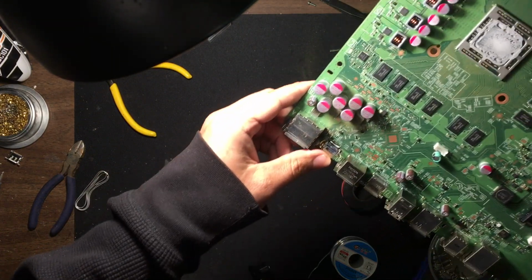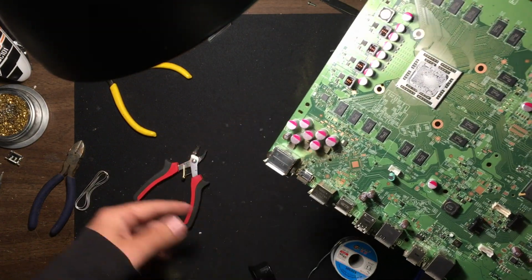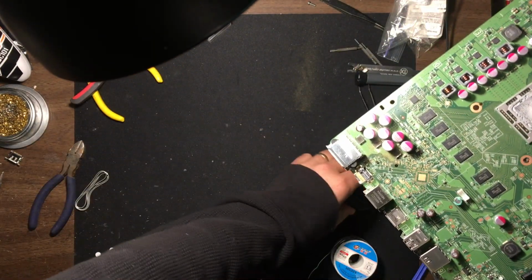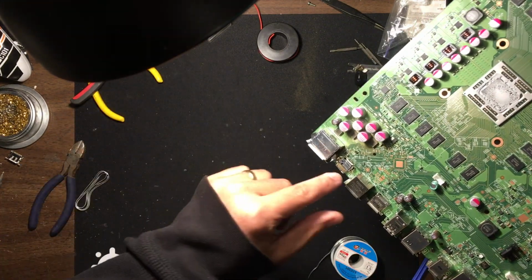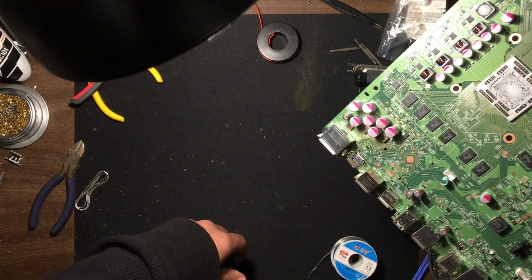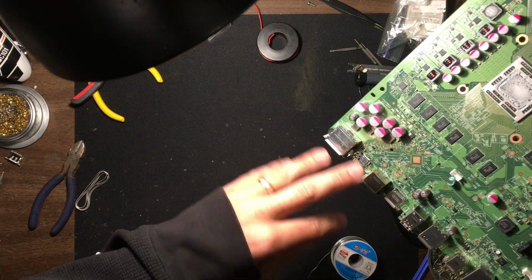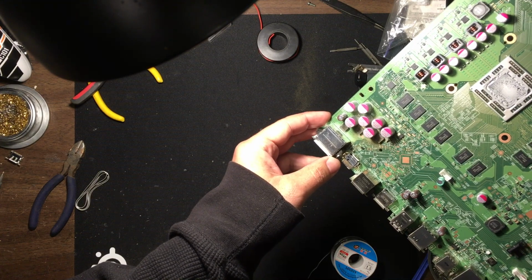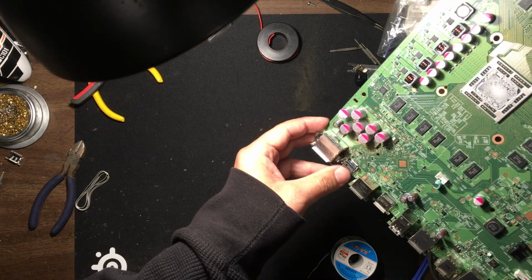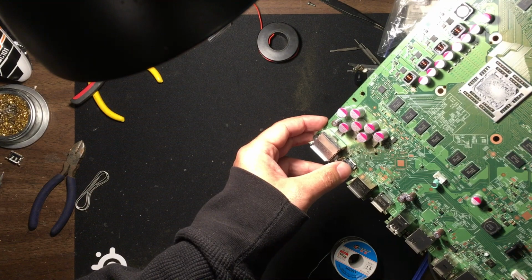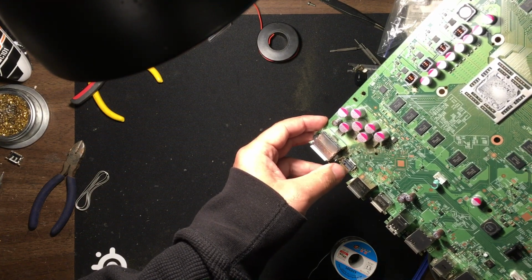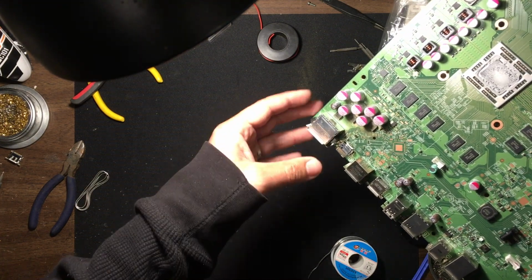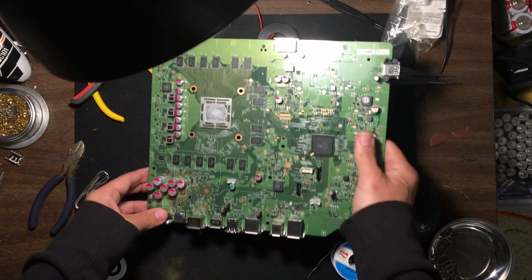So I already have the low melt solder on there, if you can see that as a strip. So I should be able to just solder, and then that should pop right off. So we'll do that right now. And again, the thing I'm most worried about is these pins, because if you damage them, you're in trouble. But once you have everything off, it's a matter of just putting everything back down again. It's a bit easier to put back on than to take off, because you can basically solder down these 19 pins before you solder down the thing that actually holds it in place. All right, anyways, we'll see actually how that goes.